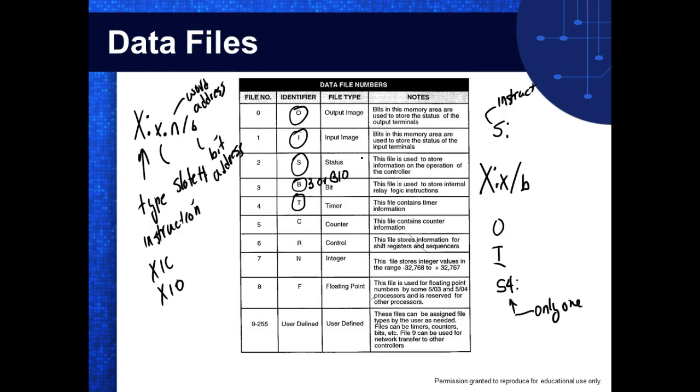And that's what you're doing when you tell RSLogix your model number of your PLC, then that's going to establish what instructions you actually get in RSLogix, right? You understand? It's just like on your time base. They say that we have a 1, a 0.1, a 0.01, and a 0.001, right? I'd have to look at that, but it all depends on the PLC.